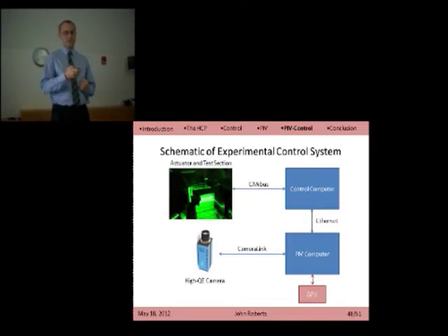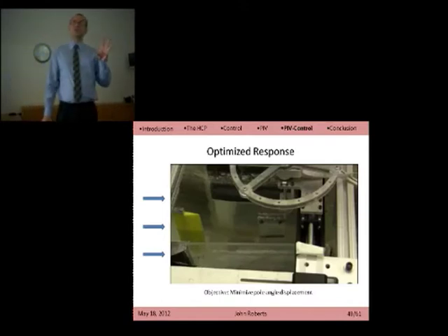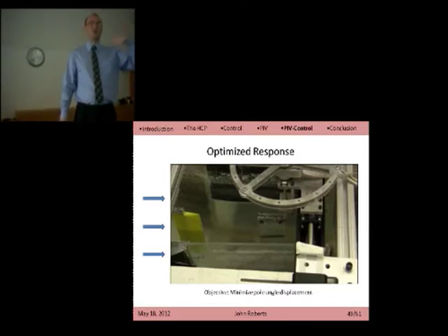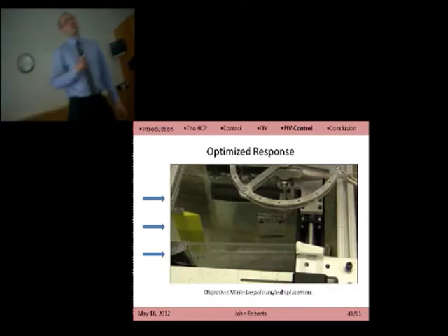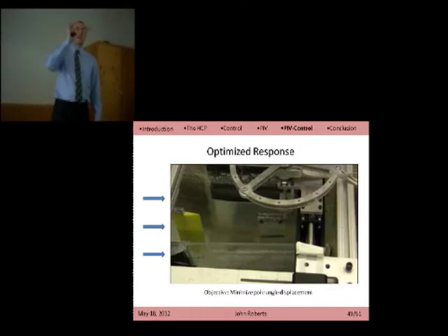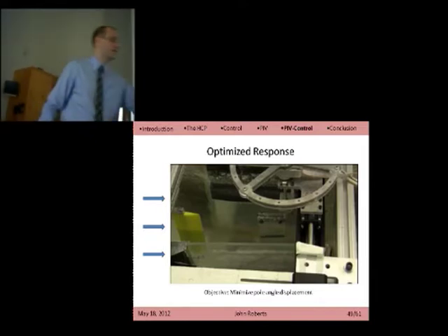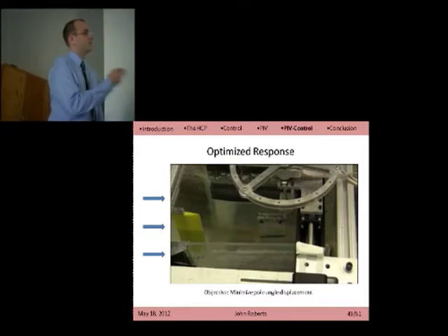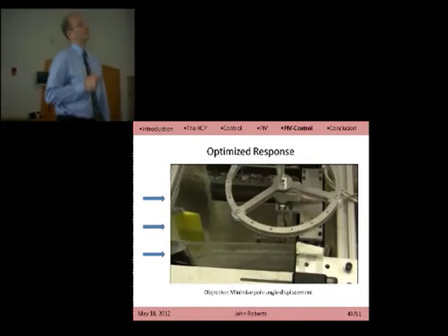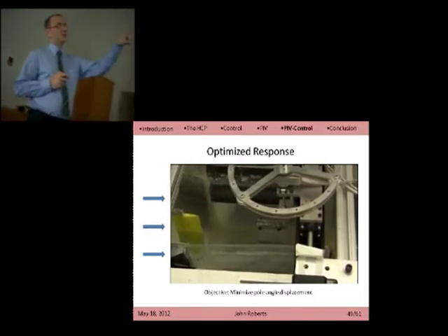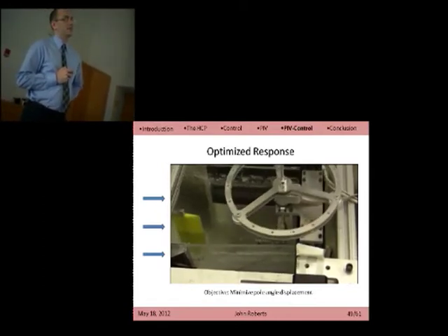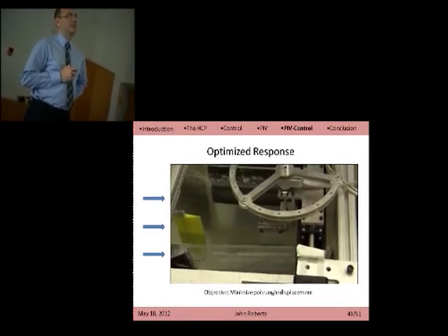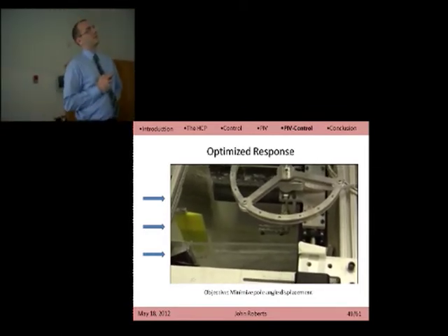Let's use some compensation. So here, using the same methodology that we used in the first half to track the step, we now design, through iteration, a compensation trajectory that will minimize the deviation. This is trying to minimize the pole angle displacement, so not how far the cart moves, but how far the pole goes from the upright. So, designing a compensation trajectory to minimize the effect of that, you see the cart moves, but look at the violence of that kick to the side. So we'll see another vortex come by, and the pole has a relatively small deviation because the cart sort of runs underneath it. Show one more.